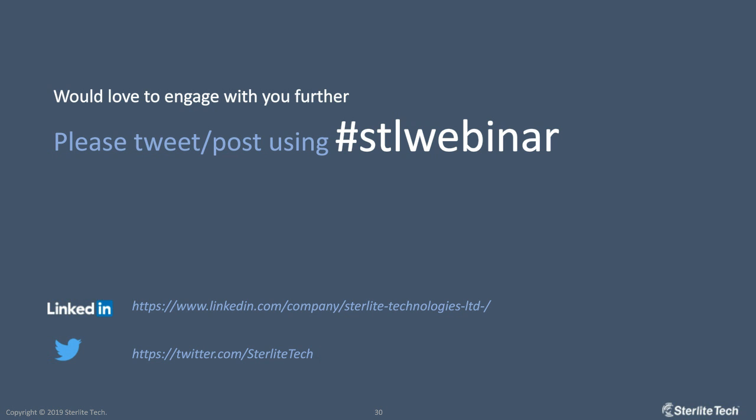If the question is whether these technologies are available in India, my quick answer is yes, sub-6 gigahertz we can deploy today. The E and V bands are not available today. They have still not been released by the government, so that's not available. But free space optics and Wi-Fi, as I said, are unlicensed and available as well. And mid-millimeter wave, just to cover that off, today you can use for licensed microwave backhaul, but for 5G NR the auctions are scheduled for sometime late next year, or this year, or early next year. Yeah, okay, it might have been the government release that was specific then.